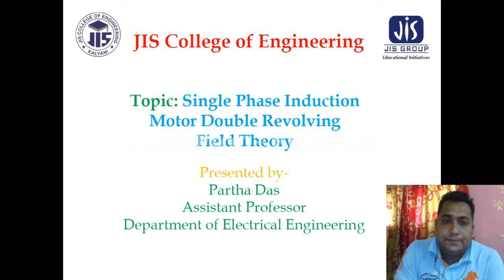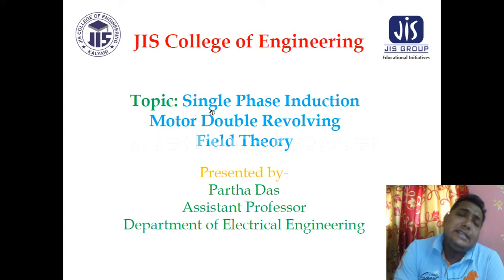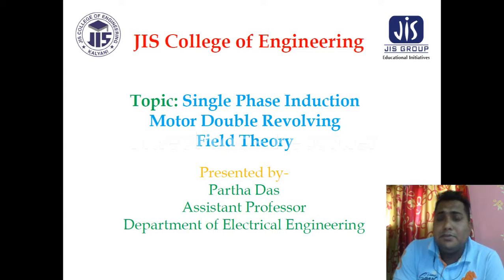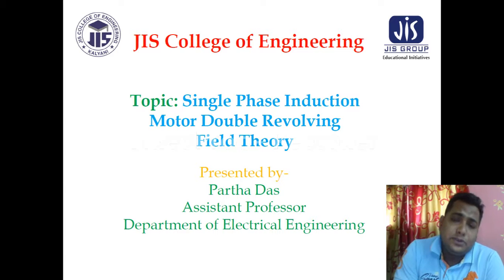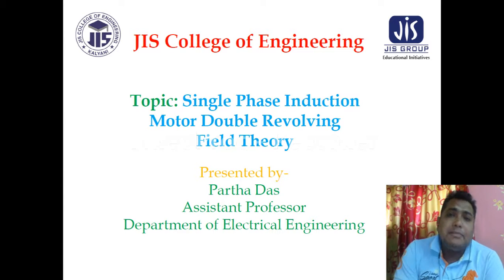Welcome to my class. So today's topic is single phase induction motors double revolving field theory. It is a very important topic because, as we know, single phase induction motor is not a self starting machine, so we have to give some external force to make it start. So why is it not a self starting machine? What is the funda behind that, we are going to discover today.